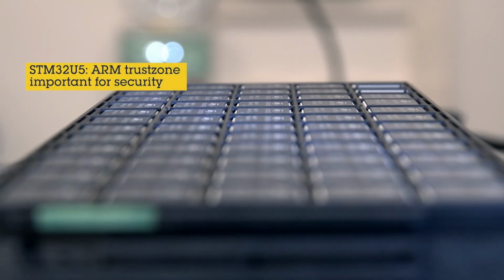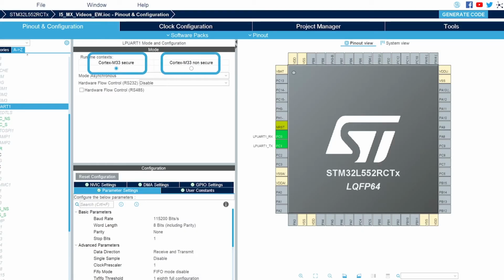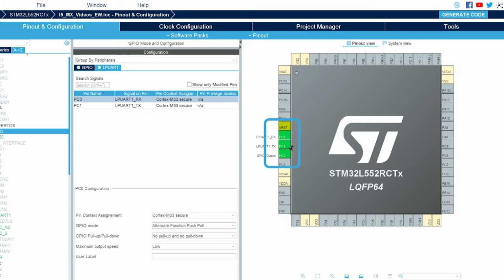The new STM32U5 has ARM TrustZone. This brings additional complexity since you have to work with multiple projects, the secure and non-secure ones. Do you wonder how do you set up execution context for middleware, GPIO or peripheral? Thanks to our CubeMX graphical wizard, it is now possible to assign to each of them secure or non-secure part, and all this before you generate your C project.